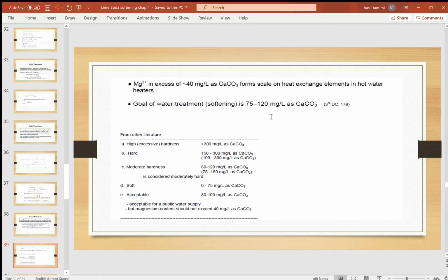All right. Of course, this is something that has been already said. Once magnesium is exceeding 40 milligram per liter, this is the stage where the magnesium starts to create problems of clogging, deposition, scale formation, and so on. And as we said, the practical limits for total hardness go from 75-80 to 120, but usually we stick to 120 milligrams per liter as total hardness of CaCO3.